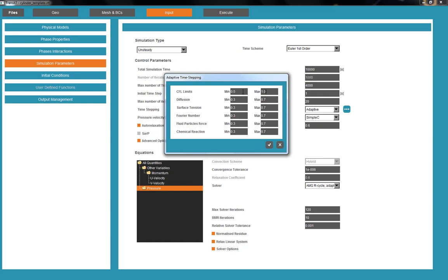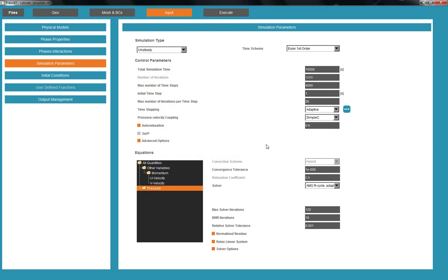Therefore, based on the flow velocity and grid size, as a larger CFL number allows for a larger time step, we'll keep it at 1. We also need a coefficient or a control based on the diffusion, which we'll set between 0 and 2. For auto relaxation, we'll define 0.83.